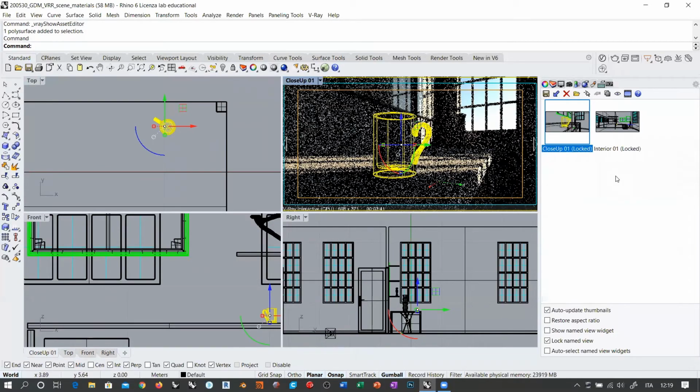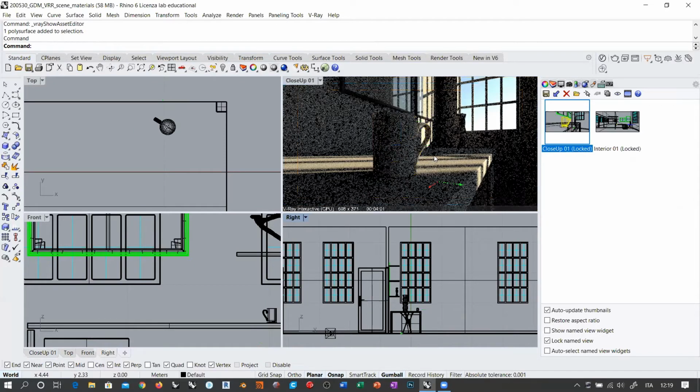I don't want to reload the V-Ray render settings right now, because they also have depth of field and a higher render output resolution, so the render would last more, and I don't want this. I want to keep the workflow as smooth as possible. So I'm just changing the camera to this position.